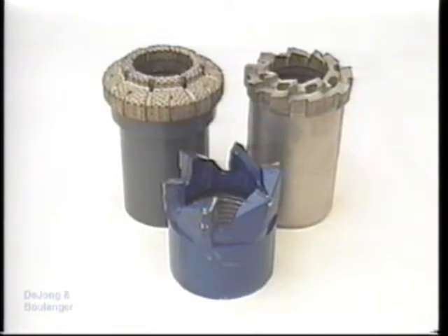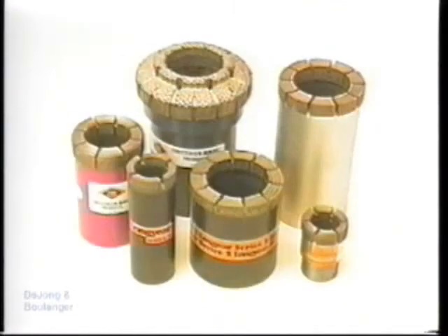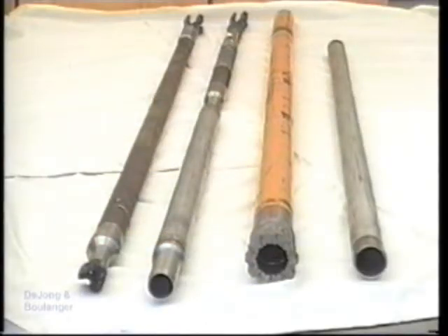Coring drill bits come in three basic types. Pictured from left to right are the diamond, carbide, and sawtooth. Diamond bits are the most versatile, since they can produce high-quality cores in materials ranging from hard or very dense soil to hard rock. As shown, coring bits come in a variety of shapes and sizes, each of which is suited for a specific situation. Some systems, such as the Christensen 94 pictured here, can perform multiple tasks such as drilling, coring, and sampling.